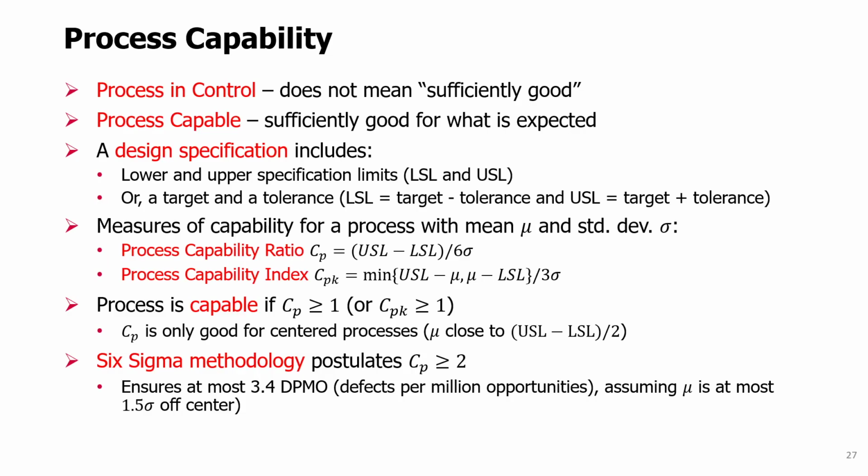Process capability, and Six Sigma. When we create control charts, which are part of statistical process control, we make sure the processes have today the same variability as they had in the past. So basically, when we say the process is in control, we say that it has a similar random distribution for some of the important parameters as it had in the past, right? We say the variability is the same, it's not bigger, not smaller, right?